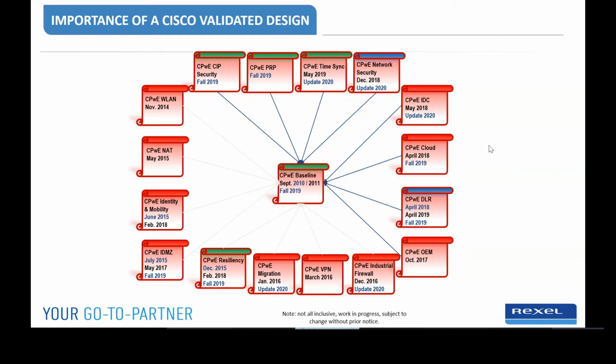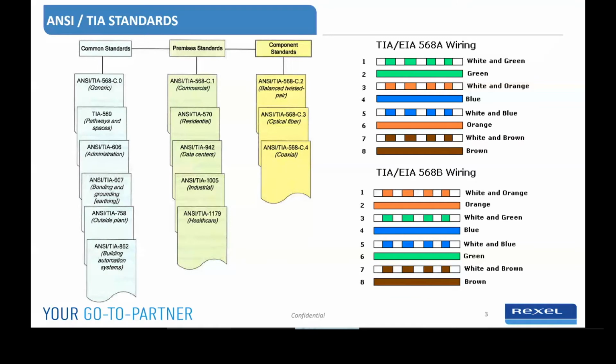Excuse me, Trevor. There's a question that came through. Doug Hoffer asked, which style of cable termination, TIA 568A or TIA 568B, is most commonly used in industrial settings? Yep, great question. It might seem a little bit backwards, but it's actually the TIA 568B.